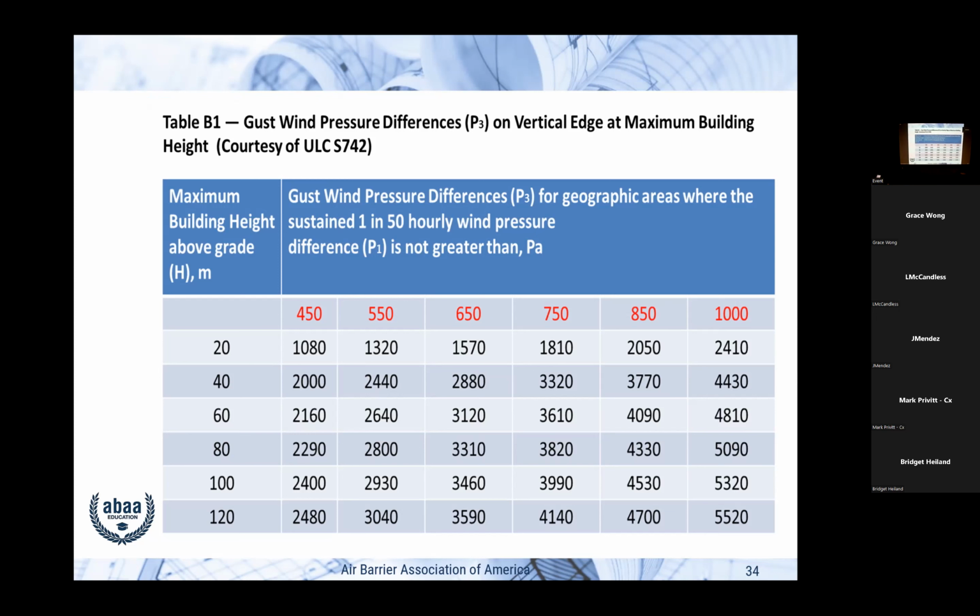Why doesn't that happen? Well, we've got wind engineers that say if we're going to put windows in a high rise, they've got to be different, they've got to be stronger, and all the rest of the stuff. But again, it goes back to air barriers, because you're going to have air barriers on a 400-foot building. And so that's the loads. Again, our saving grace is most of the material is stuck to a substrate that's been designed for these loads.